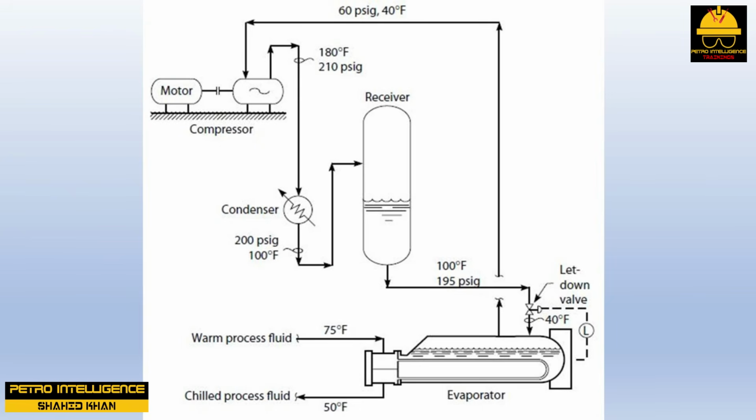Another way to reduce the compressor discharge pressure is to make the refrigerant heavier or less volatile. Adding isobutane to a propane refrigerant is one example. This will lower the suction pressure to the refrigerant compressor shown in picture and increase the actual volume of vapor flow. If the compressor is speed limited, this will not be practical.